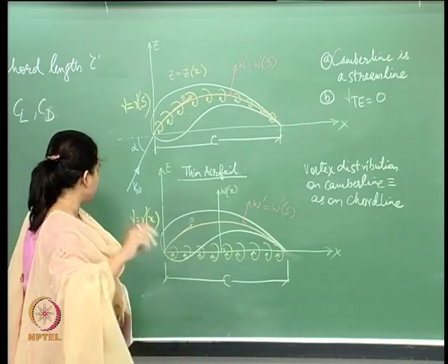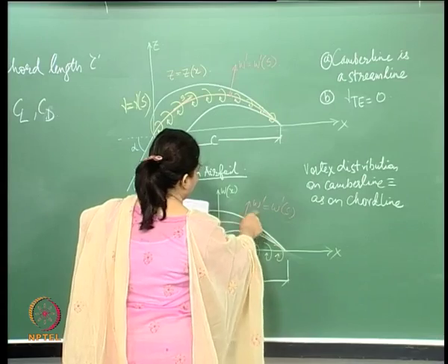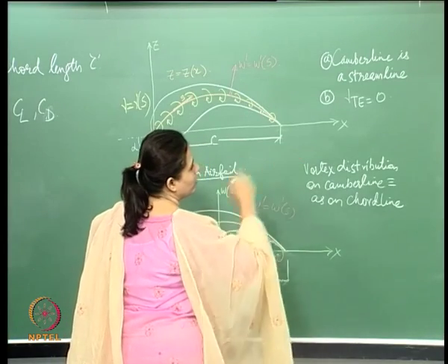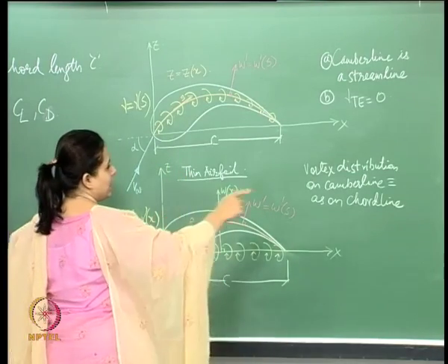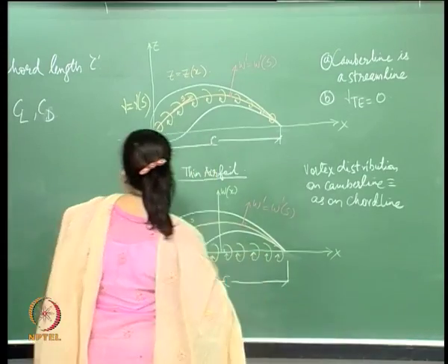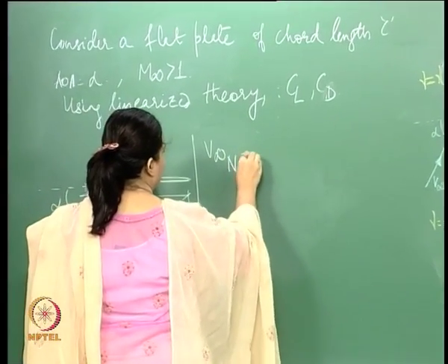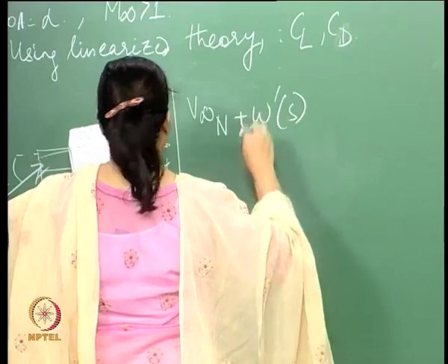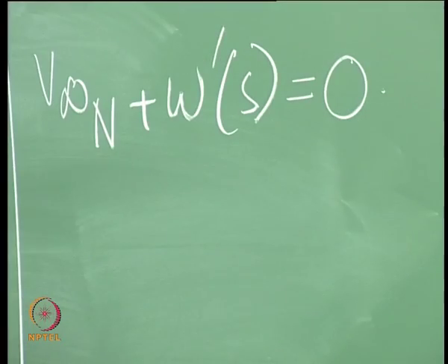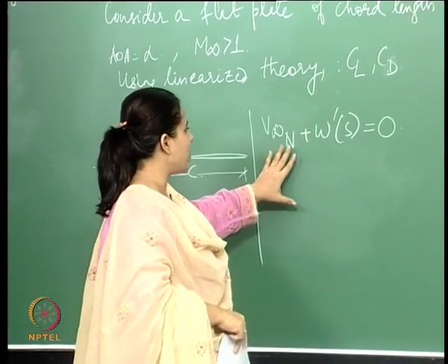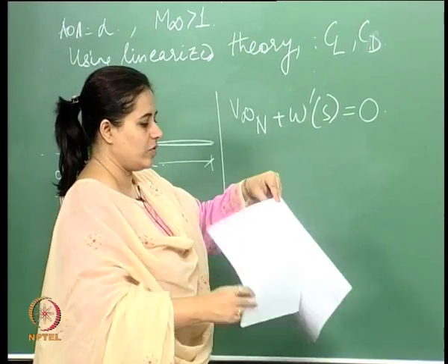Let me at least just say here that now that we've done this, we have found out that the normal component of velocity is Vn. Therefore, the total velocity induced at the point P is this, and that total normal component of velocity is 0. So, we will start from here, complete the thin airfoil theory, and then take it from there and finish up this problem.